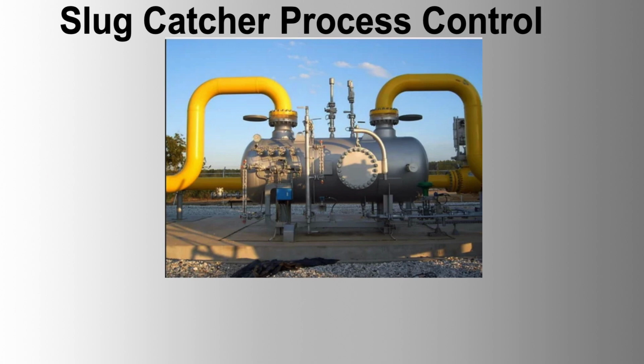5. Issue: ineffective emergency shutdown. Cause: faulty ESD systems or delayed response. Solution: conduct regular testing and drills to ensure ESD systems are functional and personnel are well trained.